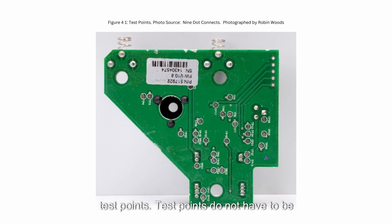of test points. Test points do not have to be an installed component on the board, though test post type devices make it easier to hold or latch a probe to a signal. A test point can simply be an area of exposed copper on the signal trace, large enough to accommodate the probe. By providing test points, we avoid the need to place probes on delicate component leads. Generally, test points are via structures that are fabricated into the board. If large enough, the barrel of the via allows the tip of the probe to stay in position.